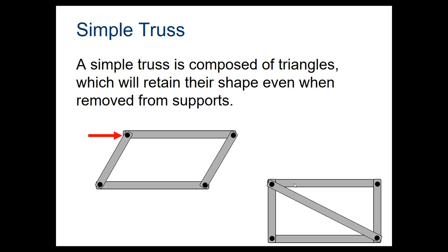And that diagonal beam is going to allow us to keep that from moving, because we would have to bend that cross piece for this to change its shape. Because right now, in this picture, this diagonal is changing as that moves. So when that moves, the diagonal distance from here to here and the distance from here to here are going to change. By adding this cross beam, now we're fixing that diagonal length.